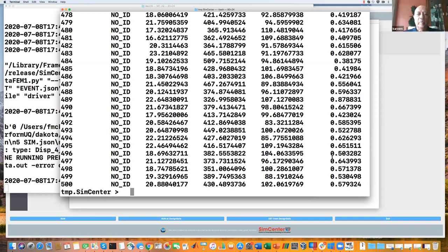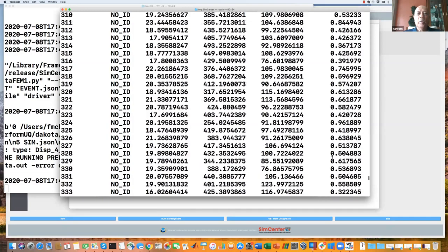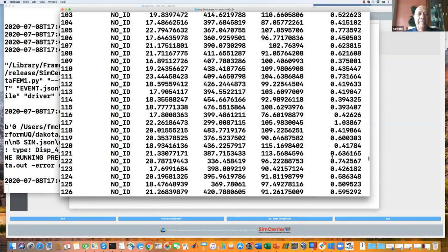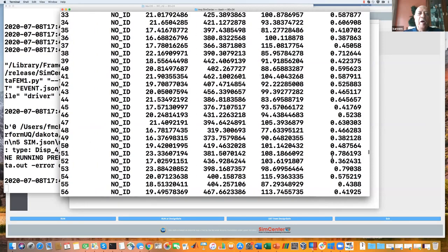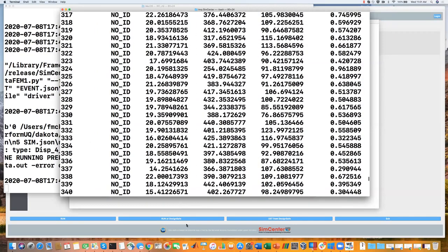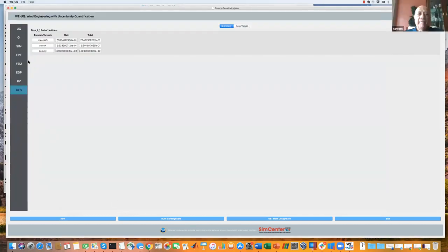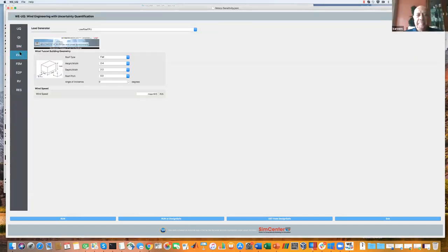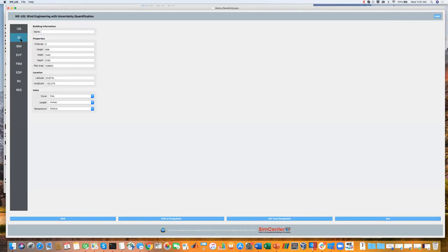Frank, the question may also be looking at how you decide the PDF, or the mean and variance, of the input parameters. I think the answer is that there's a lot of information available in the literature. You want to make sure that a quantity such as strength, which is always positive, like the compressive strength or the yield strength, typically has a log normal distribution so that everything remains positive. You don't want to use a Gaussian distribution because that will give you negative values.